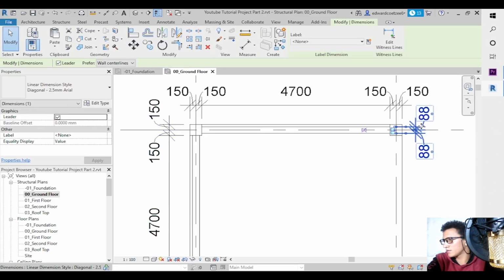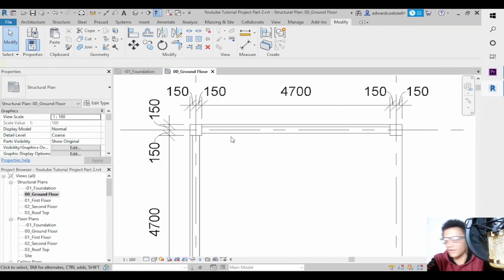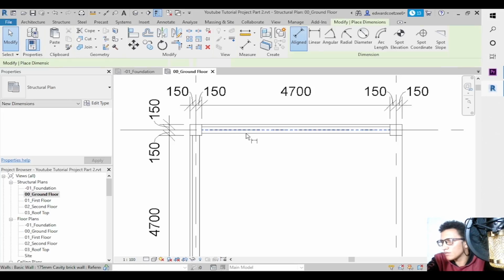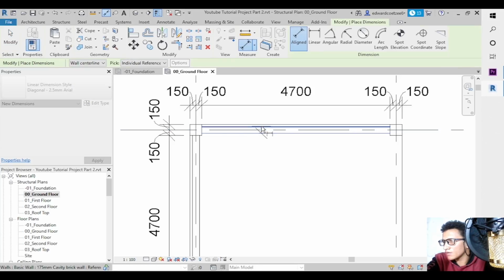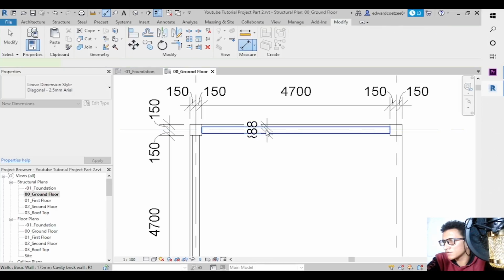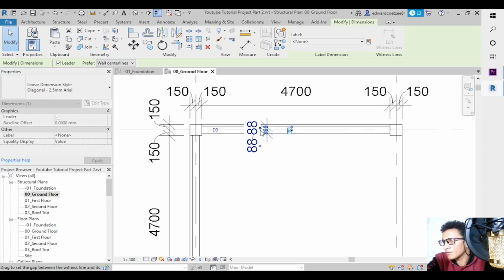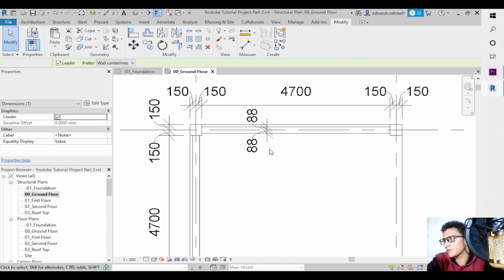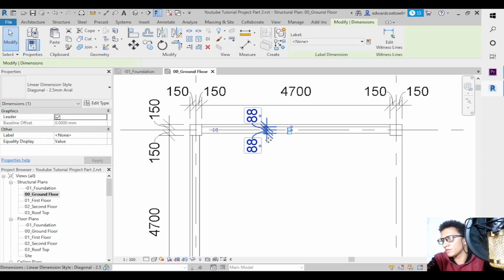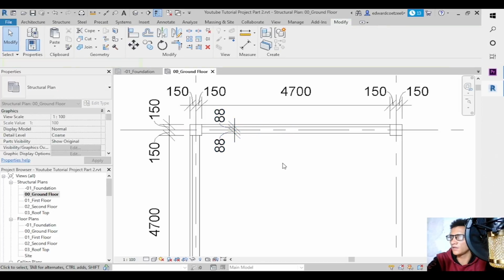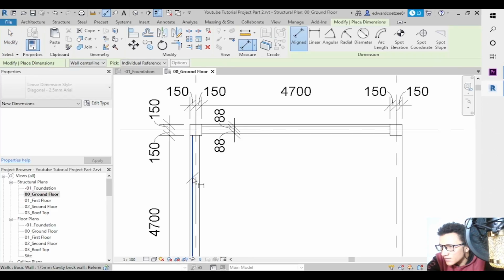Okay, this you might want to also take out now and then just go DY, insert the wall, and just do that. Usually you won't put your dimensions to interfere with the building, but in this case let's just leave it that way so that we can give an indication of the thickness of the wall.